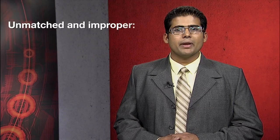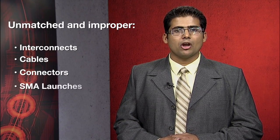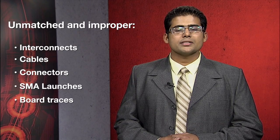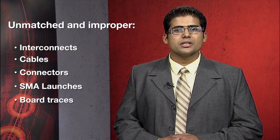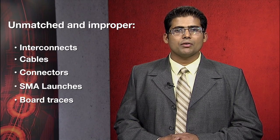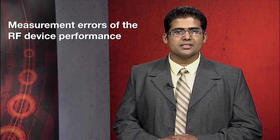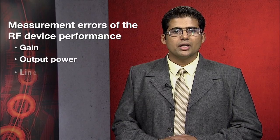In this video, we will understand ripples in RF device performance measurements. Unmatched and improper interconnects, cables, connectors, SMA launches, and the board traces cause impedance mismatch, which results in multiple reflections of electromagnetic fields and leads to the formation of the ripples. These ripples result in measurement errors of the RF performance such as gain, output power, linearity, and